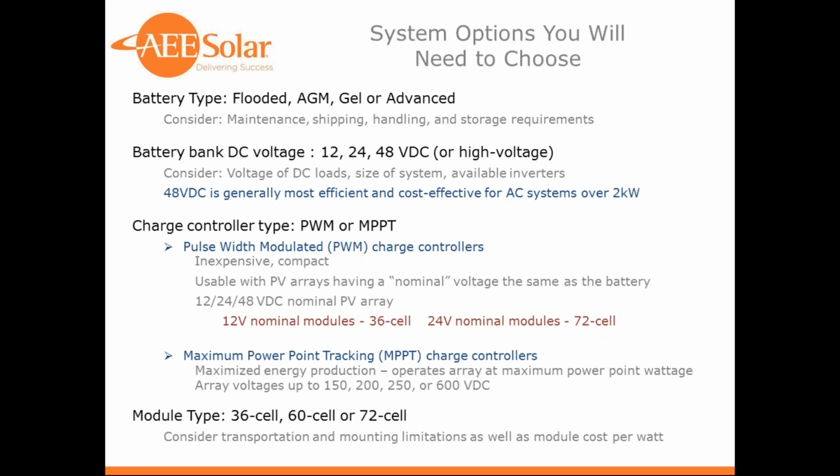There are two basic types of charge controls. The simplest and the oldest type is called pulse width modulated. It's basically, solar panel connected, solar panel disconnected. It's an on-off controller, but it does that disconnection point at variable speeds depending on the charge to the battery. So it'll have more or less time of the PV connected to the battery to charge the battery. And it controls the battery by high-speed switching of the PV array.